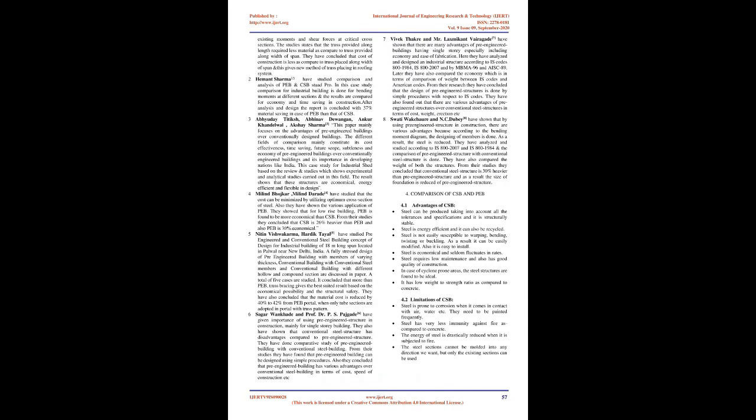It is also seen that steel has some reserve strength in it. The conventional steel buildings are stable. Usually hot-rolled structural members are used in these buildings. Here the members are fabricated in factories and then transported to the site. Changes can be made during the erection by welding and cutting process. Normally trusses are used in this system.